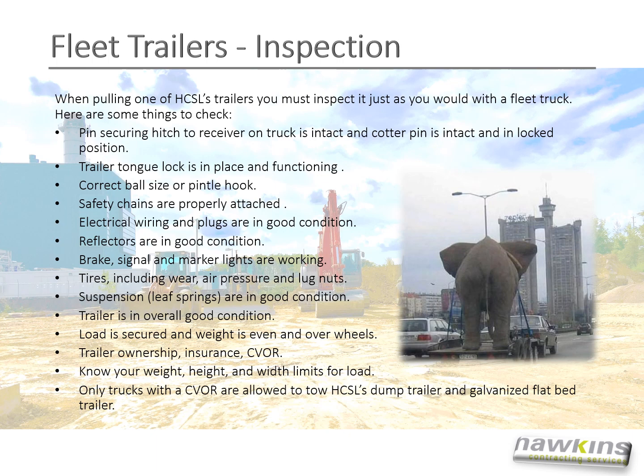When pulling one of Hawkins' trailers, you must inspect it just as you would a fleet truck. Here are some things to check. The pin securing the hitch to the receiver on the truck, make sure it is intact and the cotter pin is intact and in locked position. Check the trailer tongue lock, make sure it is in place and functioning.